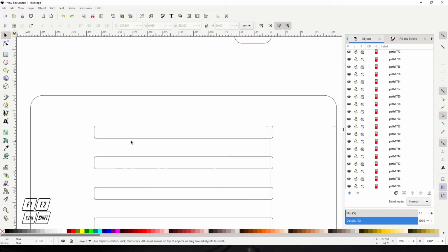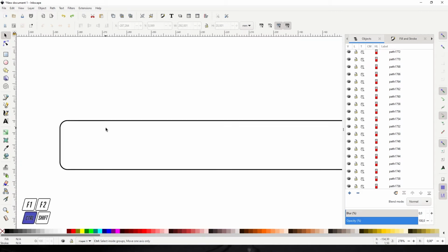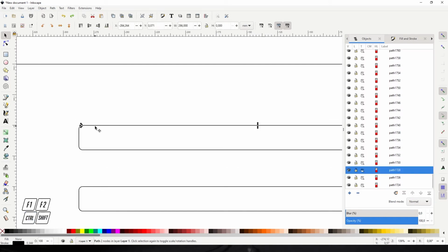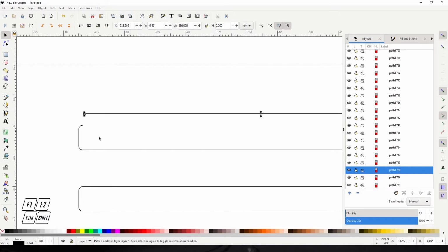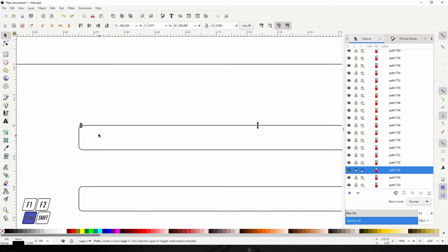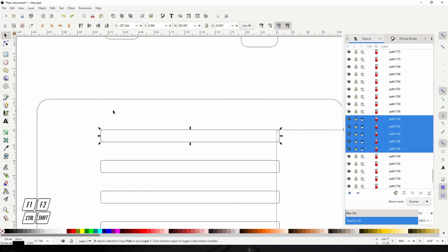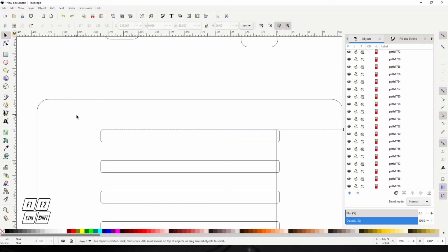First, it's necessary to check if there are duplicate elements. This sometimes happens if in the CAD software 2 lines are directly behind each other in this view. You can check for this by moving your element, and if there's nothing behind it, you're good to go and can press Ctrl-Z and continue with the joining. If there are duplicate elements, you should remove them, because otherwise, if we select them all, then the joining won't work properly. The next step is to select all of the elements that you want to combine to one shape.